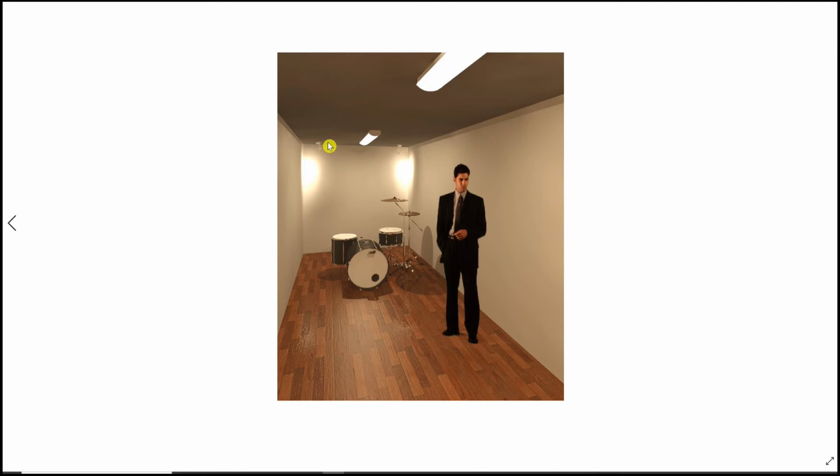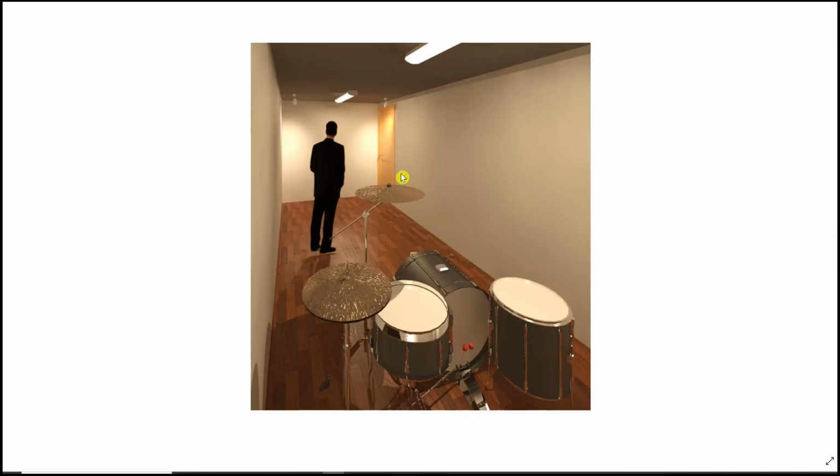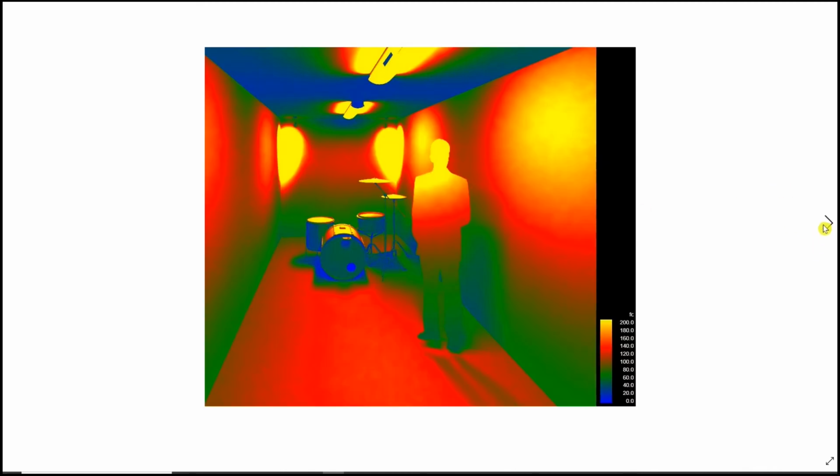And again, these heads could be moved, so you could put some artwork up if you're feeling really froggy. The reverse angle here, looking in behind the kit, there's a lot more light overhead to work with. So as we thought, there's a lot more illuminance throughout the space in general. You're pushing up into the ones, the red here, the 140, 160 foot candles. It's above even the high one for the gym, so it's quite bright in here. And then you have those intense areas in the corners. So that may or may not be desirable.